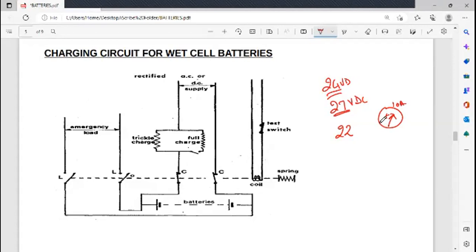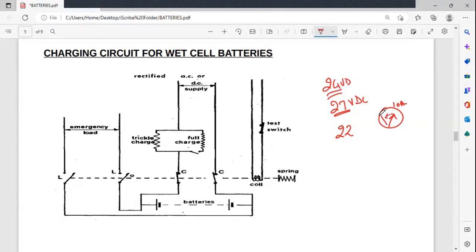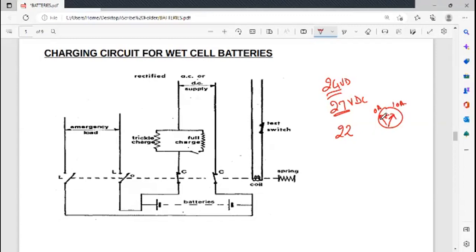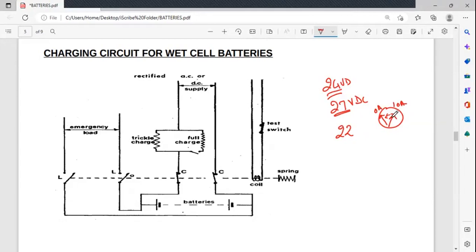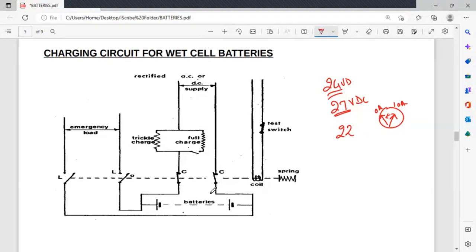And then it will be so low that you think it is actually 0 amps. But there is still a very, very small current, which obviously on this particular meter you can't see. But if you disconnect the thing and put your multimeter in milliamps across that in series, you will see that it is still giving a charging current, but a very, very small current.